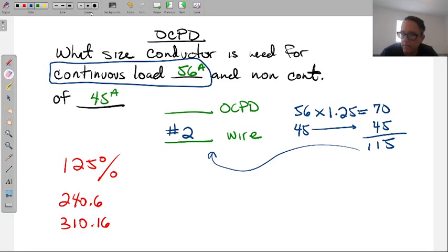And you'd have to use a 125 amp breaker. Right, so now the breaker, they don't make a 115. So here again, let me just remind you, this is where multiple choice can fail you. Sometimes nice, sometimes not nice. If I put 110 or even 100, okay, you might.